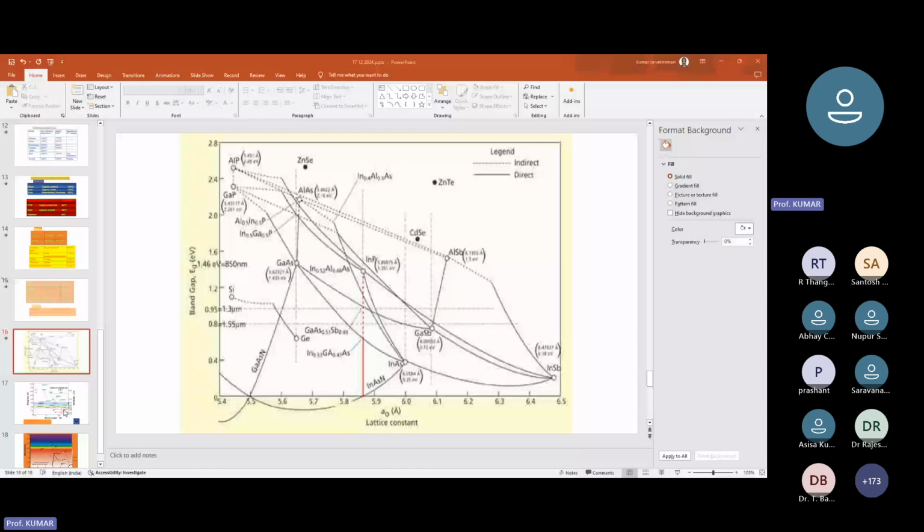One of the important things in materials, particularly in these solar cells, is that instead of having one simple material like silicon or gallium arsenide, you can tune the band gap with variations in the band energy by putting layers of materials with a different band gap, like Eg1 with a particular band gap value, like in this area, which is close to, let's say, something like less than 1.5 or 1.6.